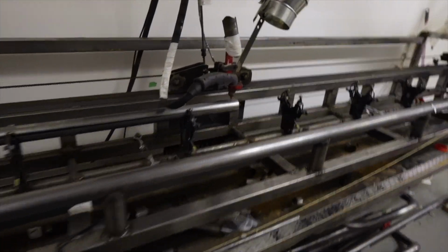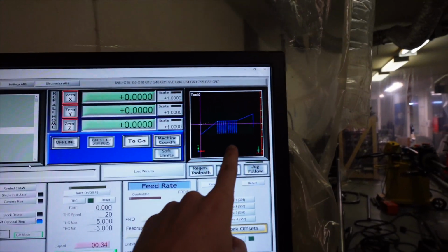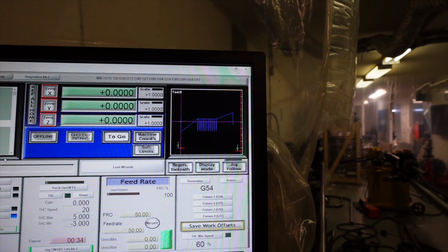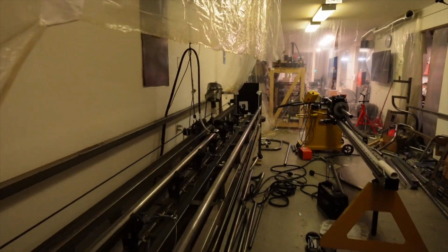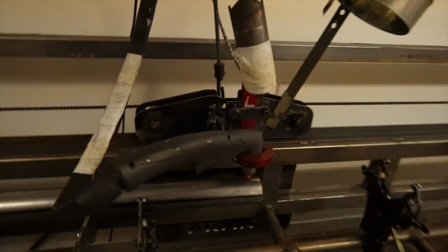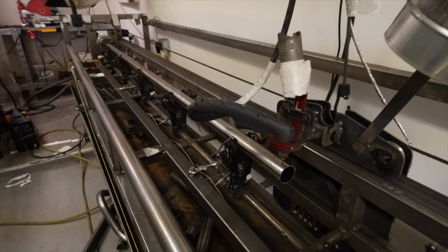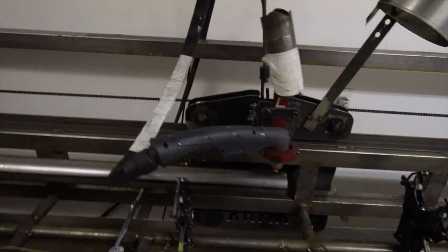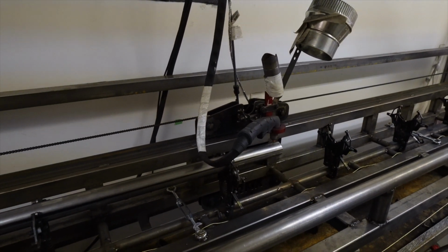This is pie cut queued up on the tube notcher. We've got the program ready here. 1 foot on each end with a 90-degree bend cut using pie cuts. Here is an 065 mild steel tube just for testing. Exhaust we would make with stainless steel, but this is just a test to check that the pie cut angles are correct and that the pie piece fits together.